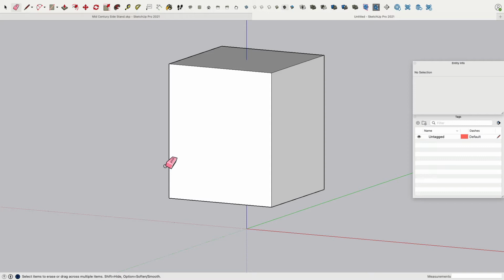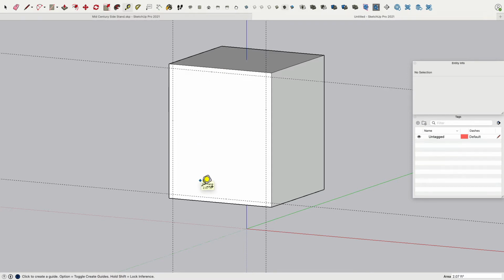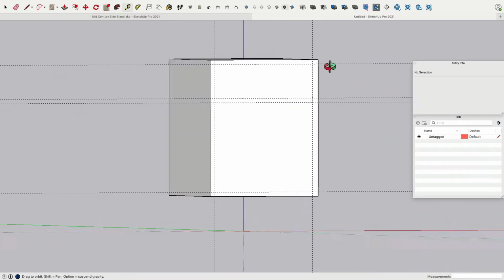We now want to have a big opening at the bottom, on top a small opening. But I would like to work a little bit more clean. So with the tape measurement tool, click on an edge, I can drag in now, for example, 15 millimeters. So that's kind of like 1.5 centimeter. Here too. There. And there. Okay. The opening should be at 120. And then another 15 for another board. Cool.